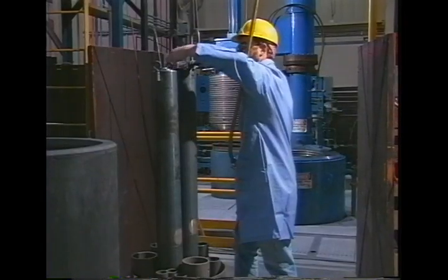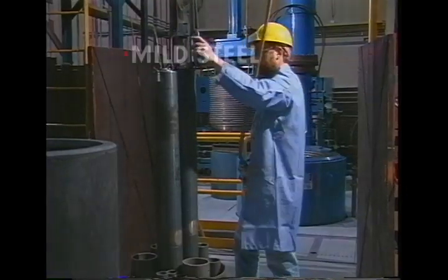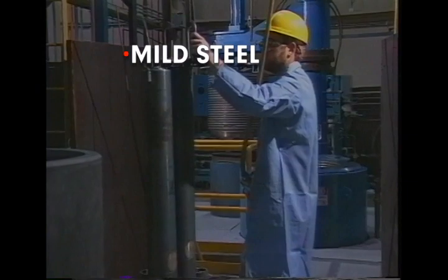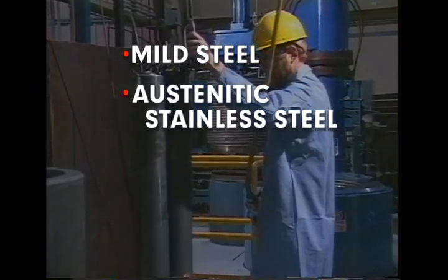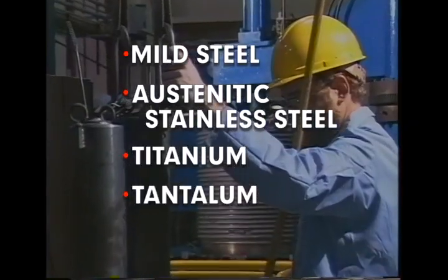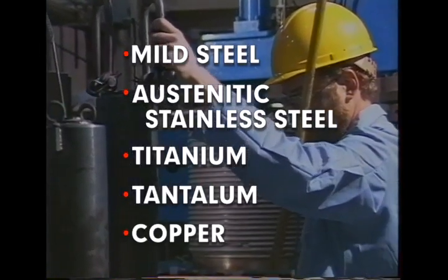Powder is placed in pre-shaped sheet metal molds. Mild steel is the most common mold material. Others include austenitic stainless steel, titanium, tantalum, and copper. For complex shapes, the molds are usually welded fabrications of formed parts.